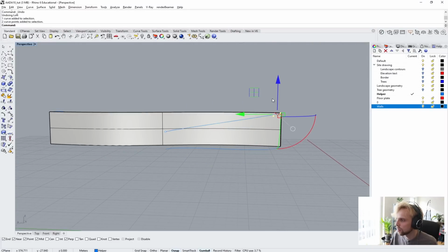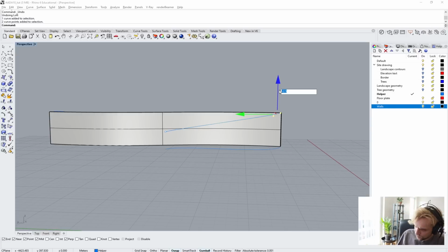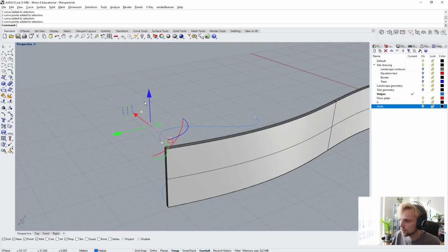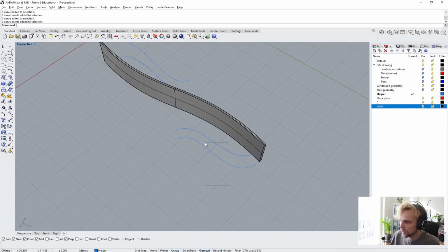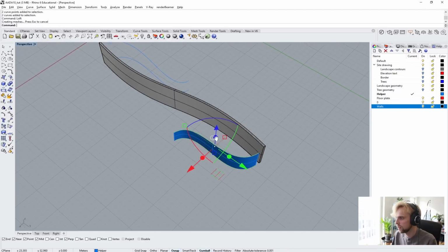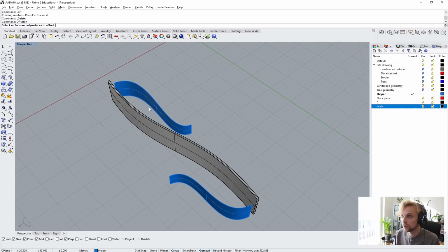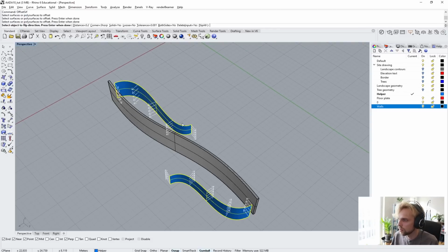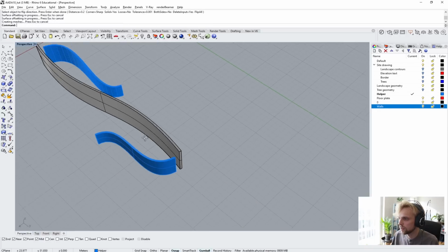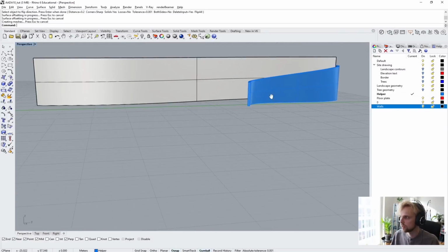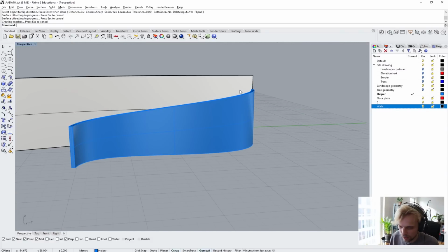And I'll just take the top control points here and I'll move them down by, let's say just 1 meter, right? 1 meter down here. And these 2 control points also -1 downwards. That's it. And then I can just repeat the same procedure. Loft, delete, loft, delete, offset surface on both of these. Inwards, inwards, that's perfect. 0.2, that's perfect. Okay, that's done. Right, so all I did was just make sure that it's not that high, right? It was way too high.